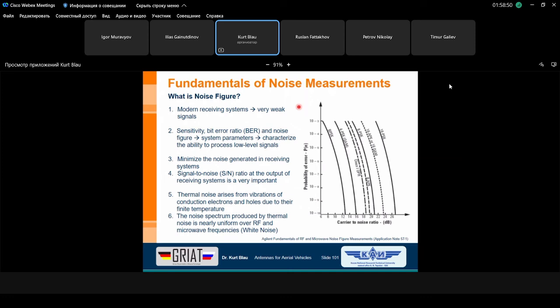All these devices, the vacuum tubes in the past, are applied for gain purposes to make an amplifier. In every case, this works only under the condition that you apply a voltage, then a current flows through the active device. For instance, in case of a transistor, it's the collector current, emitter current, base current. We have three different currents. Collector current and base current add to the emitter current, you know this.